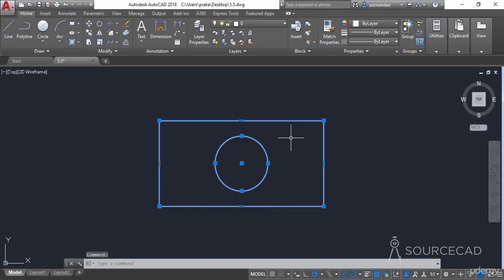Here also, when I select the circle, we have these different grips. And using these grips, we can make multiple modifications in the geometry. For example, here we have this rectangle which is made with a simple polyline, and I'll select it so that the grips are visible. Now go to any of these end grips, and when I hover my cursor there, you'll see these extra options which are available in the menu.